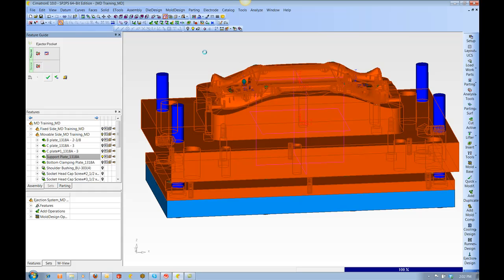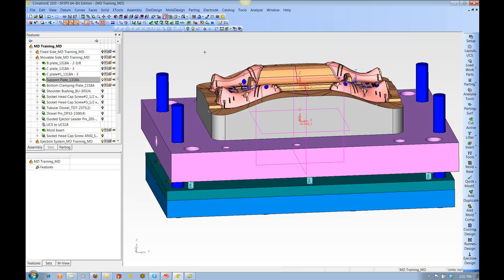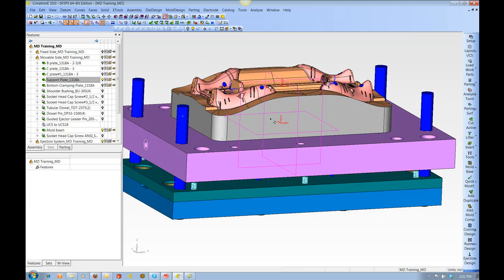Okay, let's see what happened. Oh yeah, here's something. Watch this. I'm clicking on this over here between transparent, wireframe, and solids, and nothing is happening. The reason nothing's happening is because over here I've got this set to solid, and it just means everything's in solid state, like transparent is turned off.